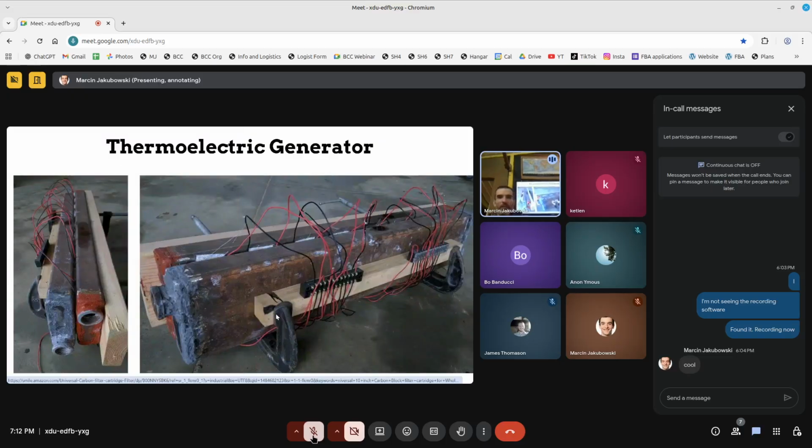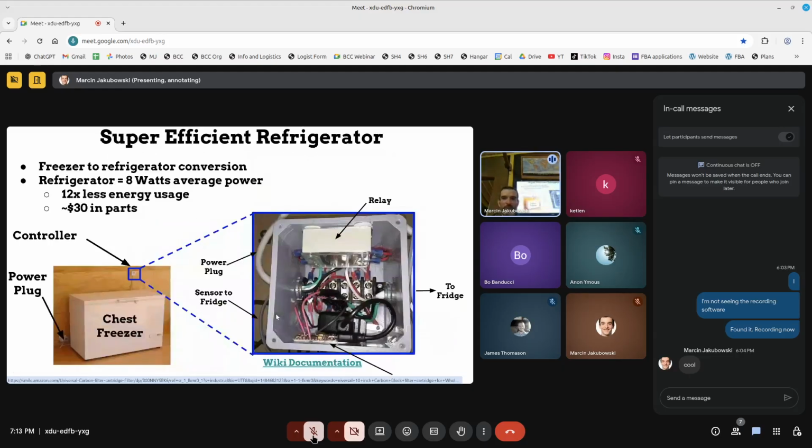We've done a thermoelectric generator. So this is hot water from the stove. So this is when we were all into stoves before we went more funky into heat pumps. But you have the hot water from a stove, part of your hydronic system. Thermoelectric generators generate electricity from a difference in temperature. So there's a cold side and a hot side. They're not highly efficient. They're up to like only 4%. But if you have a heat source, 4% of a very hot source is still considerable power. We did that. We never took that to completion or anything like that.